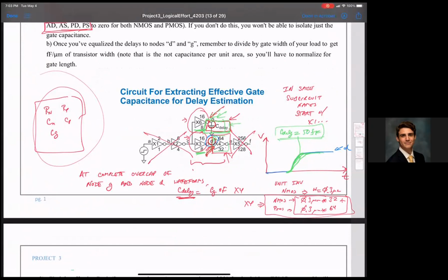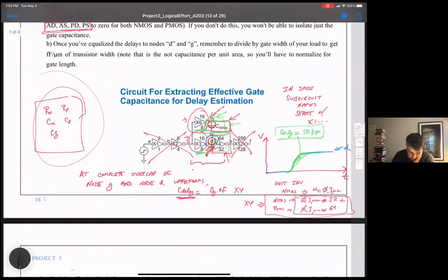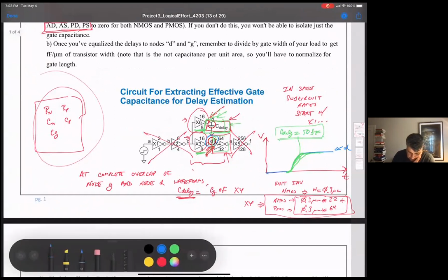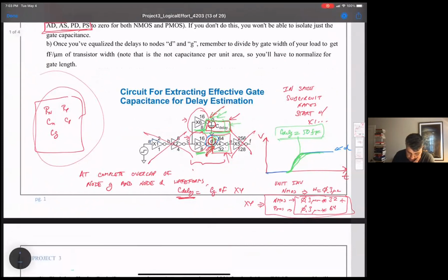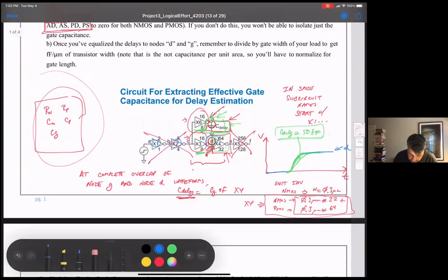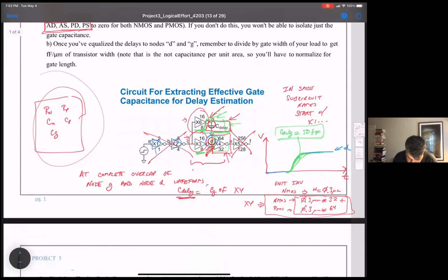Yeah, because it kind of determines the rest of it, and had to do with choosing the unit width that you're going to start with. So the first thing to remember is that although these X1s, X2s don't mean larger than unit size, these numbers below do. I'll just stick with blue. So these numbers are the transistor sizes that you guys should be using.